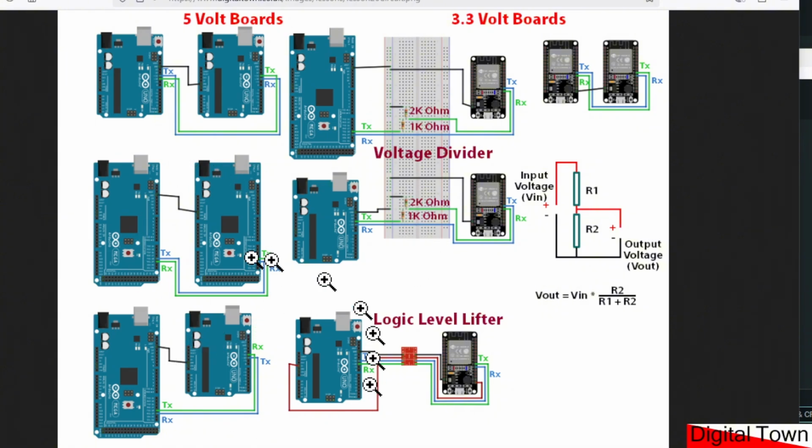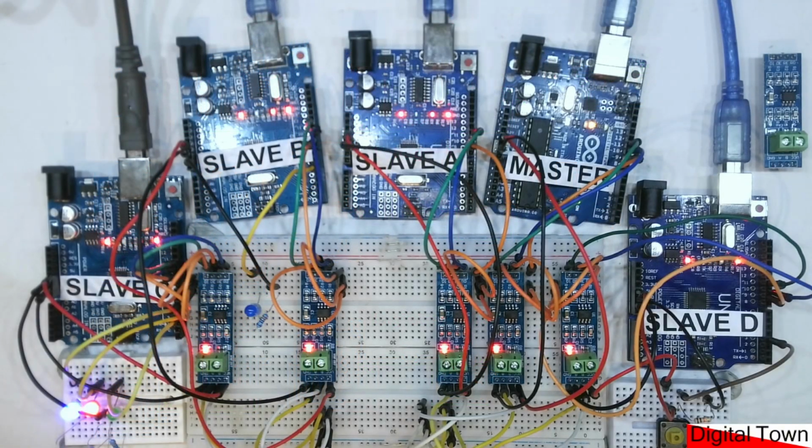But in all of these systems, it has always been just the two boards speaking to each other through the TX and the RX pin, or with the Arduino UNO, those are using software serial versions of the TX and RX. Now, much as connecting two boards together is useful, there are times when you need to connect more than two Arduinos together. And this is a RS485 network.